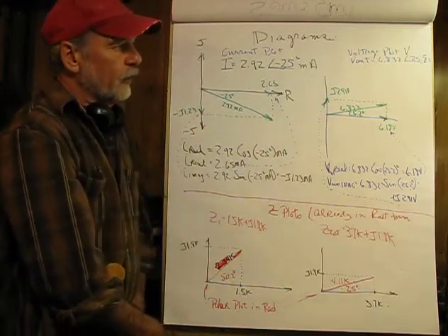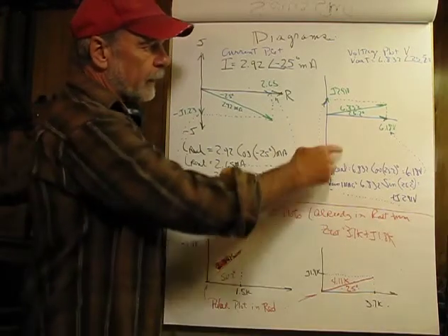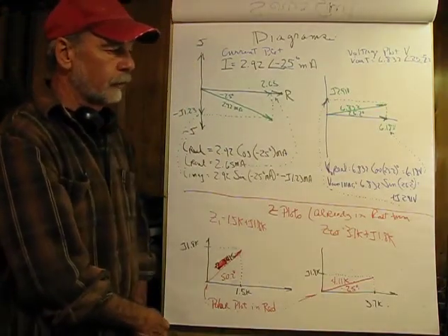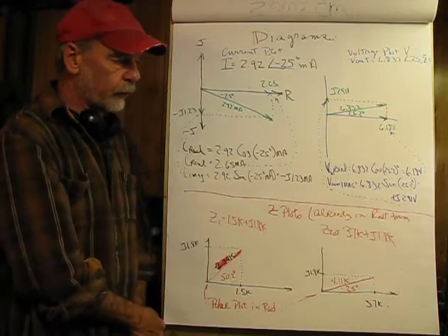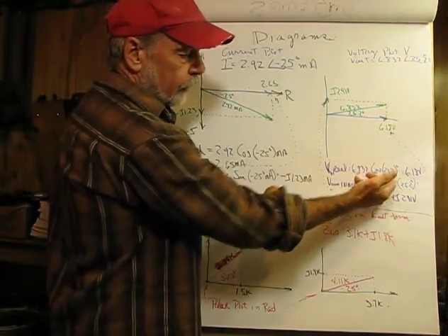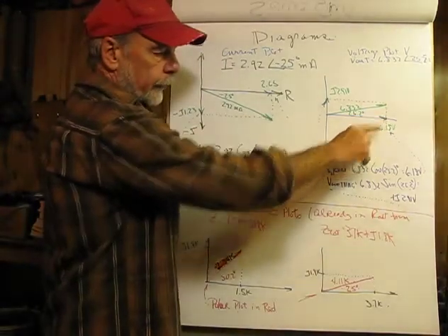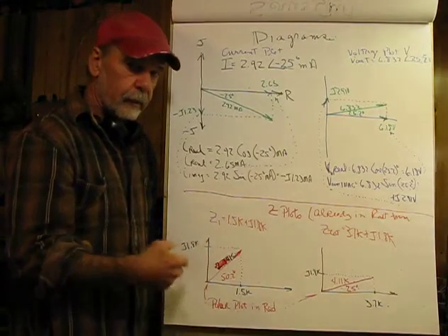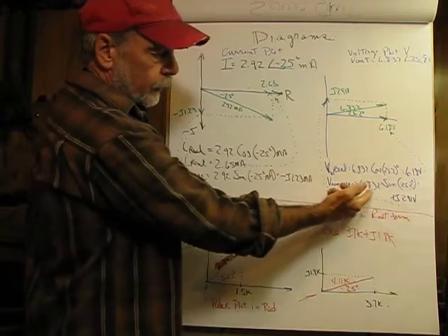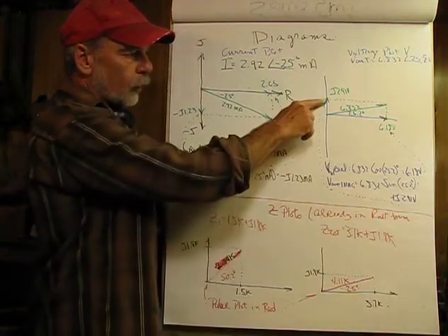Now let's do the next hard thing, and that's the voltage plot. So again, it came out in polar form to be 6.832 at 25.2 degrees. So first off, we'll find the real component, use the cosine operator again, which gives a real value of 6.18 volts. So I'll put that phasor there. And next I need the imaginary component of the output voltage, and that's going to be the sine, and that'll give us plus J 2.91 volts.